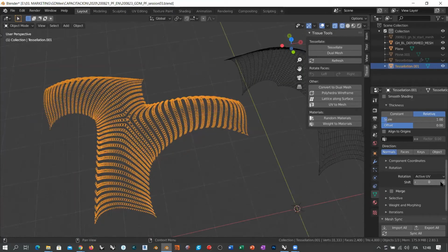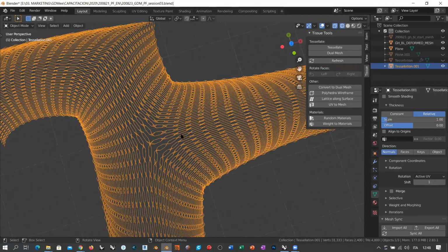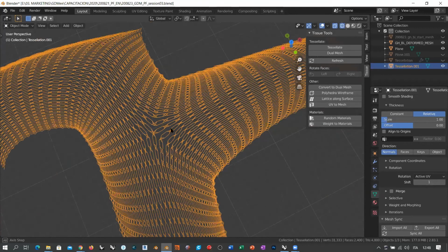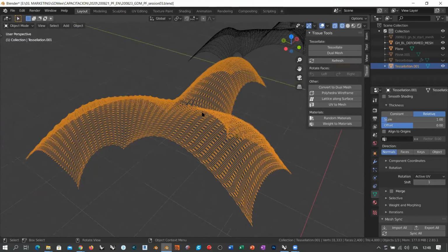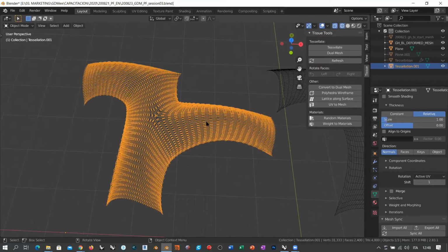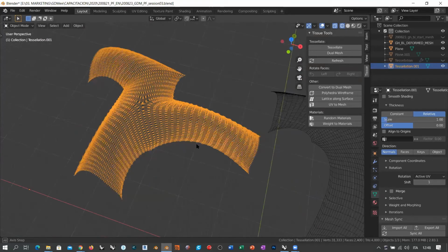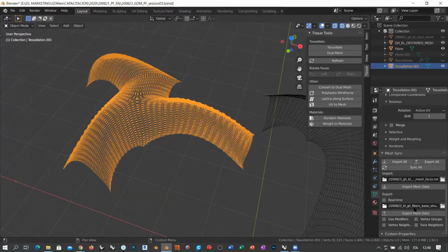And we can also invert the direction by shifting the rotation. Okay, so now I have a truss system made up of chains of connections along the loop lines. This doesn't change anything because in the end, in Grasshopper, we will be following the stress lines. So the fibers will always come up according to the stress lines. So this truss system here is affecting more the aesthetic of our geometry, of our fiber system, not the function. So if I go back here to export, you see that everything is still the same. I re-export mesh data. This is overwriting the old version.